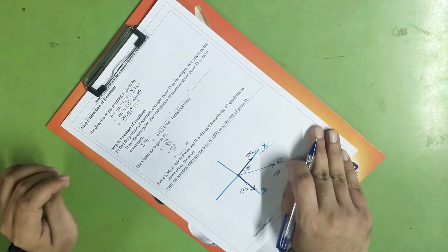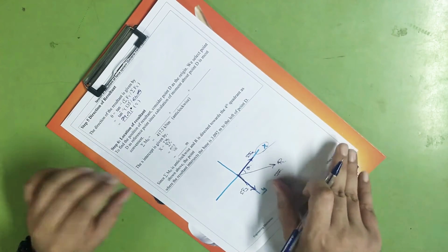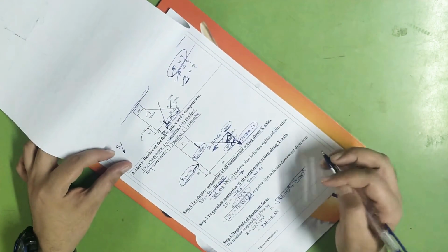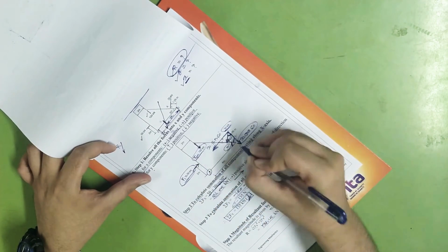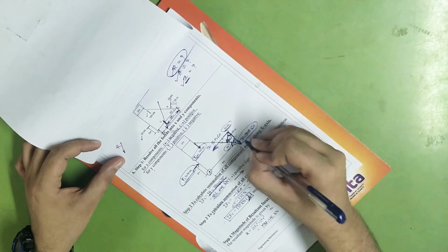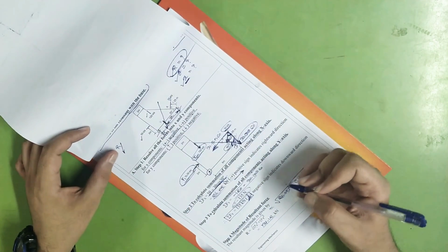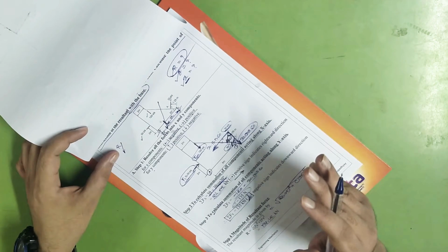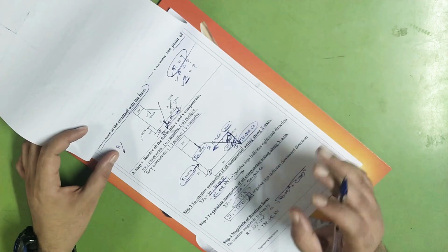Now, with this we will go for the location of the resultant. To find the location of the resultant, we have to first find the summation of moment. Here the very important thing is that we can calculate moment either about point O or about point D, as given over here. But for whatever point we are calculating moment, we must know the distance of the force from that particular point.